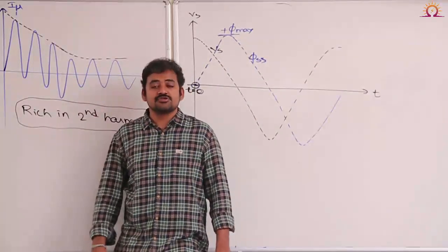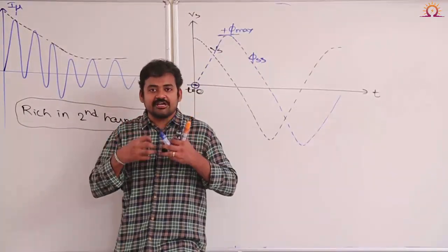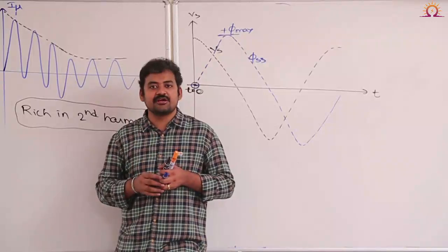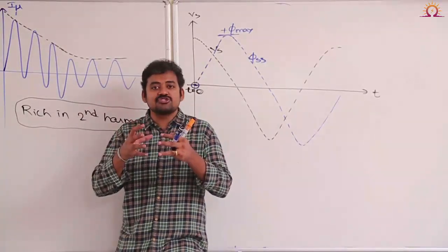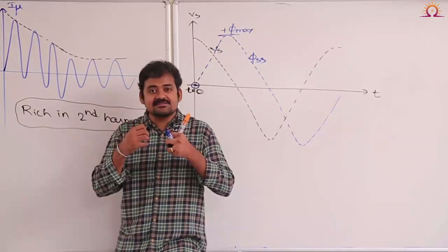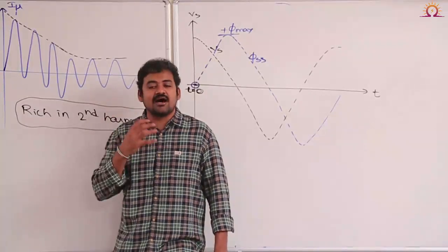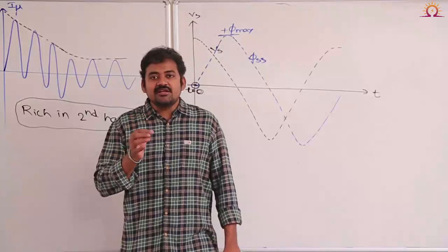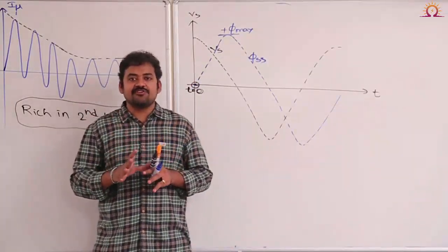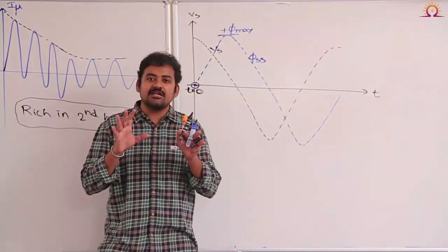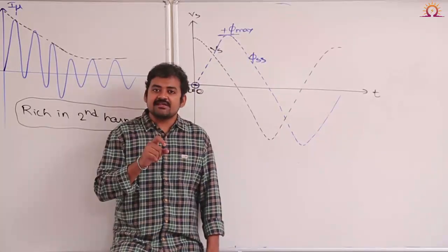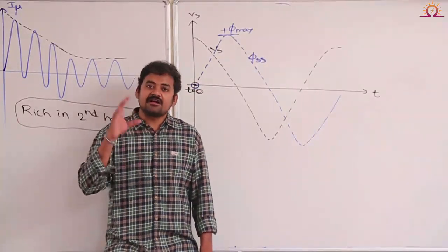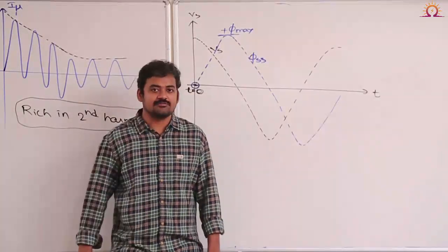But if it is a short circuit fault current, it will be continuously available till you clear that fault. So whatever protection equipment we are using, like relay circuit and circuit breaker, it must be in a position to sense whether the coming large current is inrush current or fault current. Why? Because inrush current is a natural phenomenon and it will die out automatically after 5 time constants, whereas short circuit current is a forced phenomenon and it will continue to flow till you clear the fault.